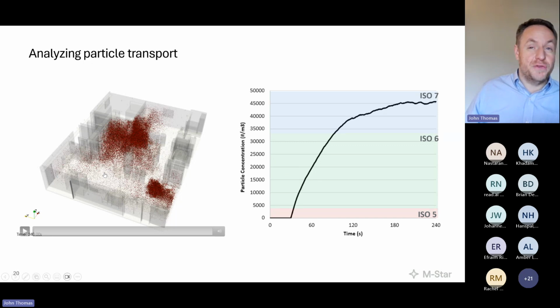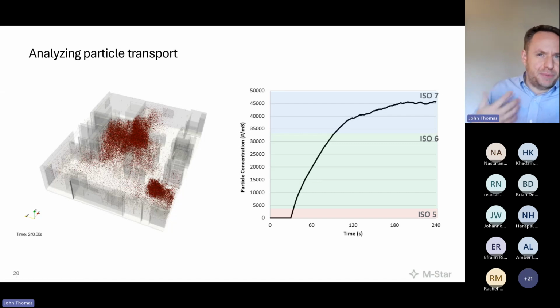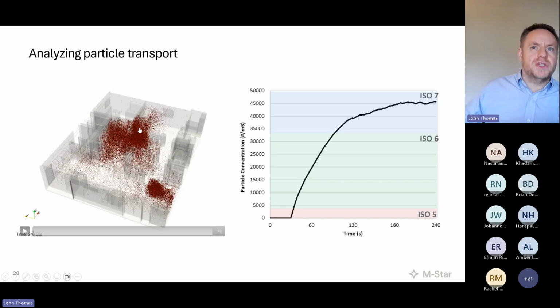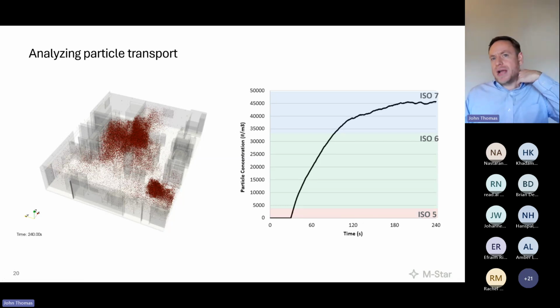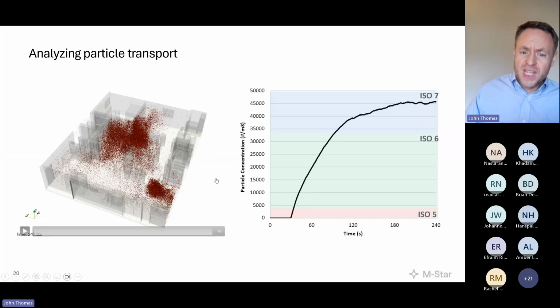Move, get out, or stand near your vent. Or more importantly, let's change your venting configuration. But again, going back to the original point, this multi-physics simulation is in play. We're not taking some mean flow field and throwing particles on there and seeing how long it takes to drain. We're actually watching these particles be dynamically emitted, dynamically ejected, and leave the system to see what sort of particle counts and distributions we get as a function of person count, person duration, person degree of gowning, and venting configuration. Pretty neat, as it were.